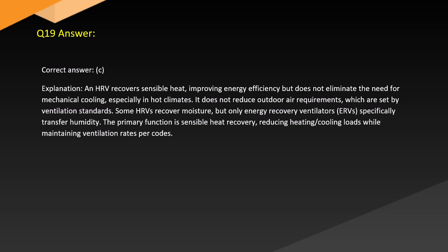A HRV recovers sensible heat, improving energy efficiency but does not eliminate the need for mechanical cooling, especially in hot climates. It does not reduce outdoor air requirements, which are set by ventilation standards. HRVs do not recover moisture; only energy recovery ventilators, ERVs, specifically transfer humidity. The primary function is sensible heat recovery, reducing heating and cooling loads while maintaining ventilation rates per codes.